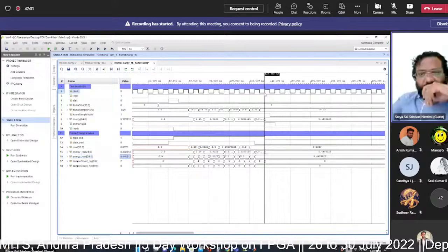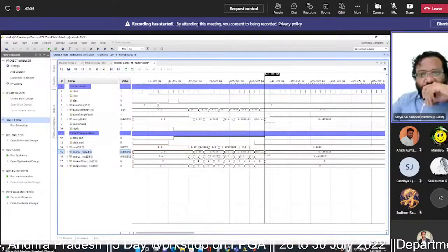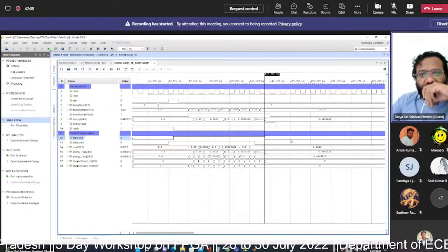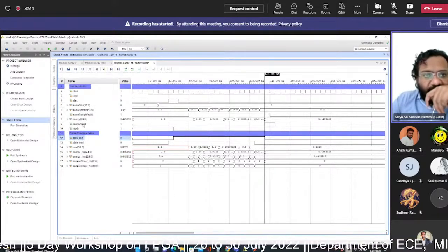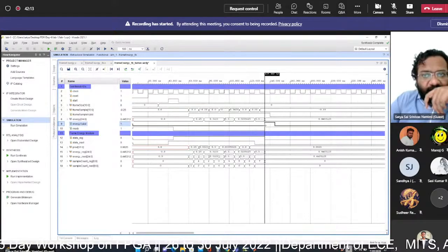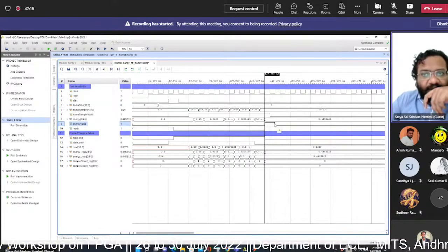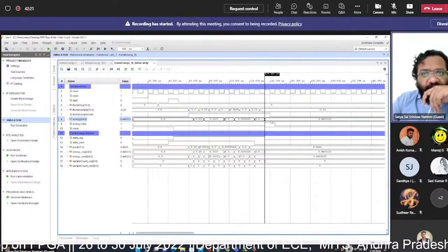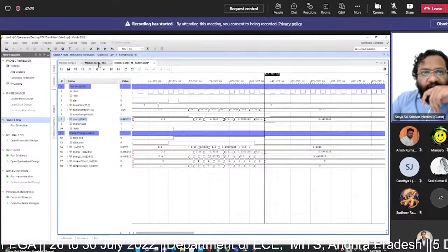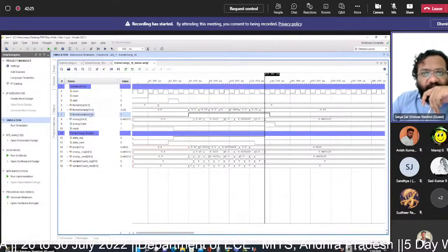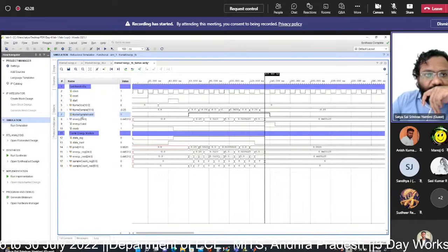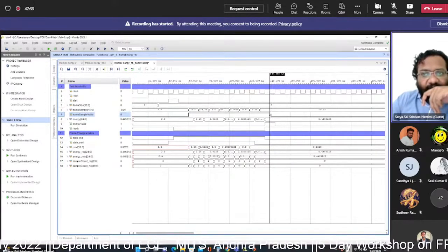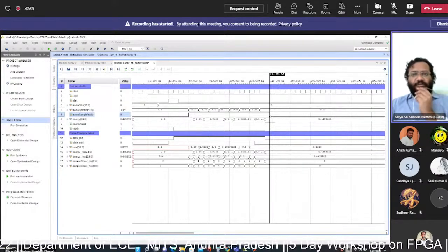And on arrival of a clock edge, the energy register holds the final value. The FSM has switched to the S0 state, and accordingly energy valid is made active high, indicating that whatever value is coming on the energy output is a valid energy output. And you can see further that frame sample valid is made 0 in that same clock cycle at the input of the module.